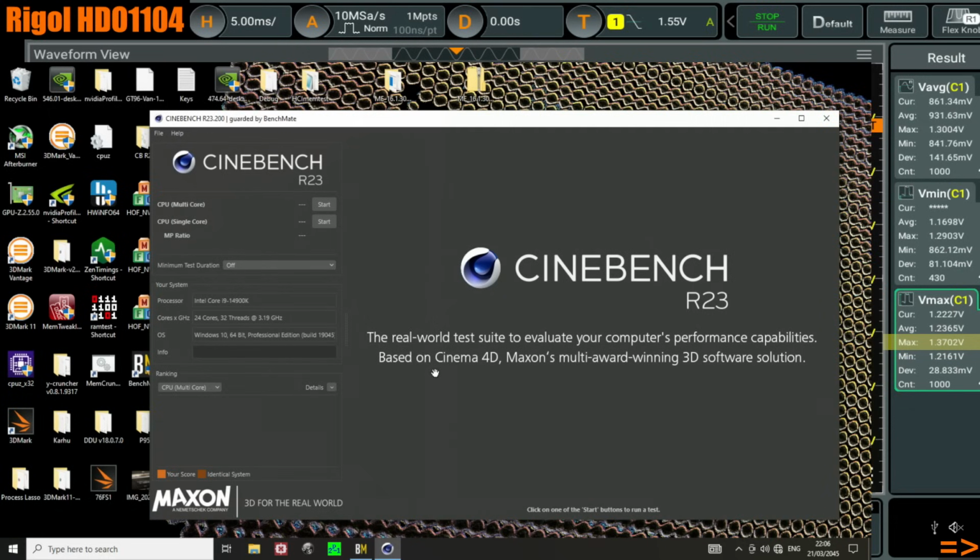Okay, that's not entirely true, but there are a few applications you can run that hit the CPU so hard that it doesn't matter what else you run, especially if you have a relatively droopy LLC. Because those applications run the CPU so hard, any other software you run will probably end up at higher operating voltages anyway because of the V-droop, so you don't have to worry about it.